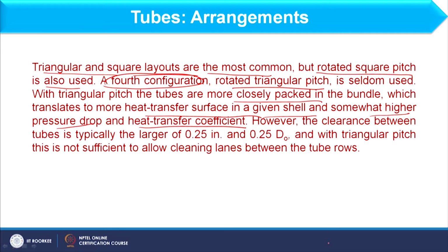So, you can understand that triangular pitch is more compact, it gives more heat transfer coefficient and more pressure drop, right. At the same time cleaning becomes very complicated in triangular pitch, okay, because the clearance between tubes is typically only 0.25 inch,